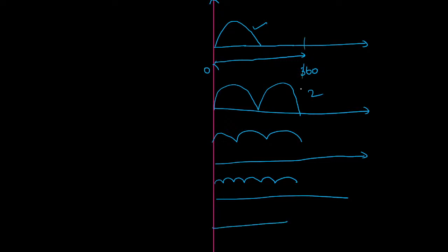But it should be exactly till 360 degrees only. From 0 to 360 degrees, how many pulses are we observing in the output? On the input side, we are giving only a single sinusoidal waveform, but on the output side, we are trying to convert it into 3 pulse, 6 pulse, 12 pulse, 2 pulse, 1 pulse. Based on this only, it will be categorized.